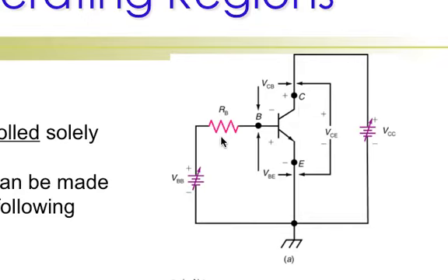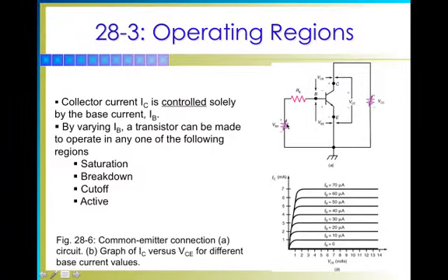Notice your flow. So in this particular case, the flow of current is going from VCC through the collector down through the emitter. This particular current flow right here is what we're going to be paying most of our attention to, because this is going to be our output. Now notice that they have variable voltages, and that's so you can increase or decrease your gain based on these variable voltages placed upon the circuit itself.